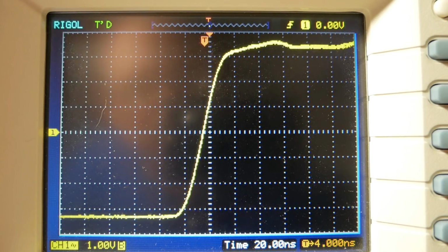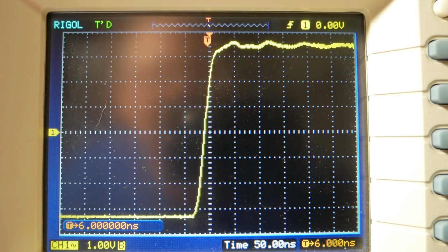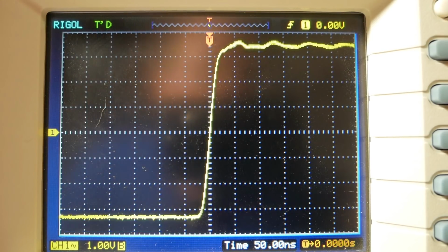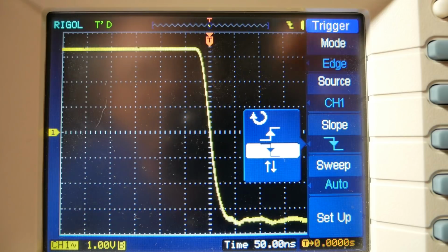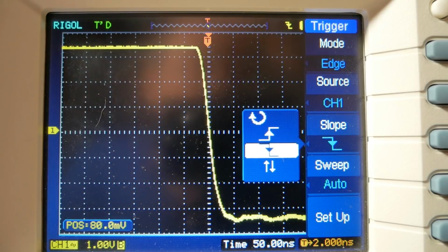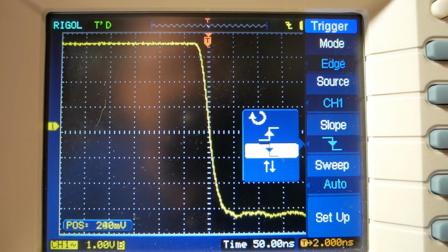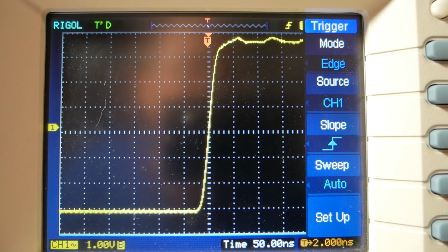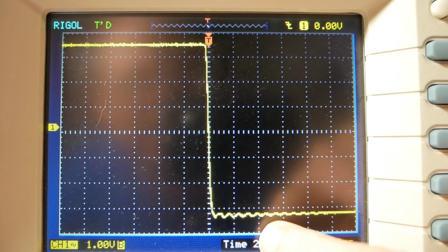Okay, what about the slew rate? Okay, we're at 50 nanoseconds just like we were before. And yeah, I don't really see any difference there. You know, I should also look at the negative going slope. I didn't show it on video, but it's the same as the other one. So yeah, not a big difference. You got to grab the right knob. So we bring this up to its normal operating voltage and getting a little bit of ringing.